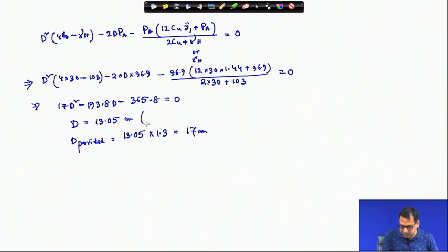Okay. You can see that for a similar problem, we have taken granular soil, cantilever in granular soil is giving 9.5 meter, then cantilever in cohesive soil is giving 17 meter, and the anchor sheet pile in granular soil is giving 3.5 meter.